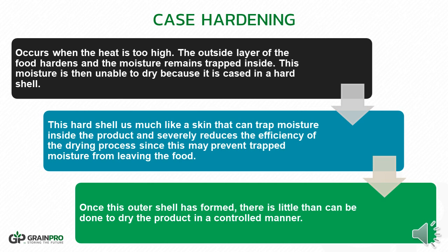After harvest, grains commonly contain high moisture. When exposing the freshly harvested commodity immediately to high temperature, the outer layer of the food product hardens. Using high temperature for initial drying does not allow the inner moisture to diffuse out to the food surface, but rather creates a hard covering around the surface. The hardened layer then traps the moisture inside the commodity.